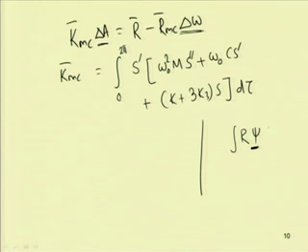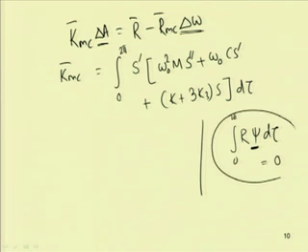If I integrate over a cycle, it will minimize. Over the cycle, in this case it is over this 2 pi. If I put this equal to 0, then I will get an equation which will give me the solution of the equation, or this will reduce this equation to its weak form.